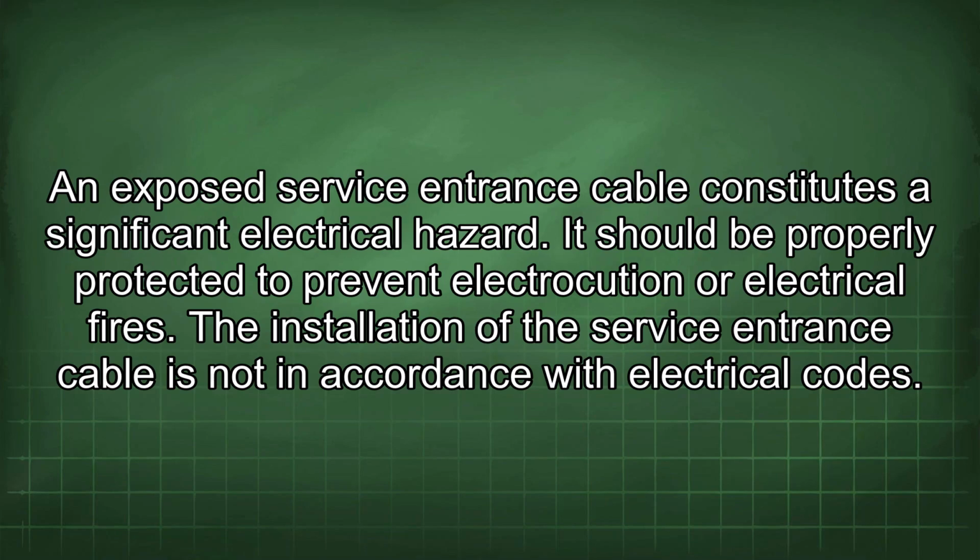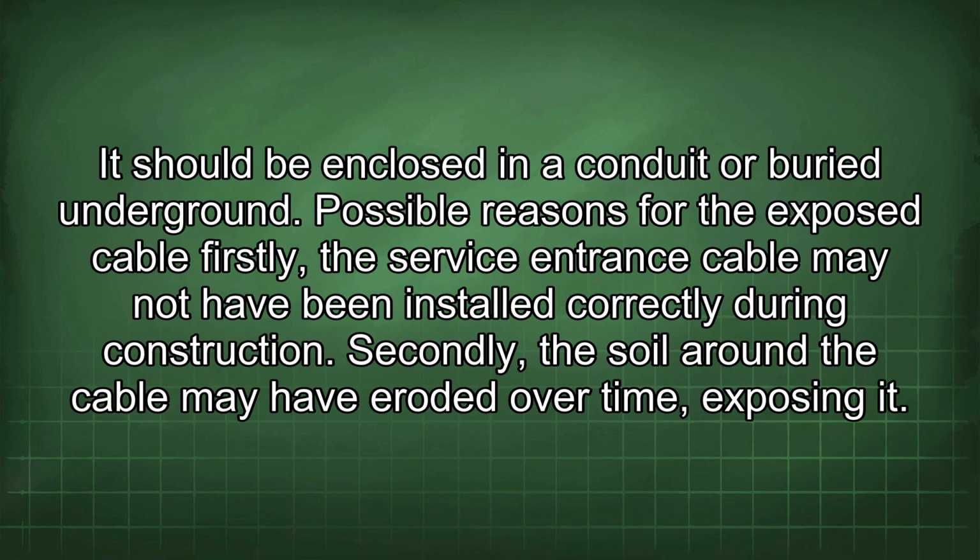An exposed service entrance cable constitutes a significant electrical hazard. It should be properly protected to prevent electrocution or electrical fires. The installation of the service entrance cable is not in accordance with electrical codes. It should be enclosed in a conduit or buried underground.